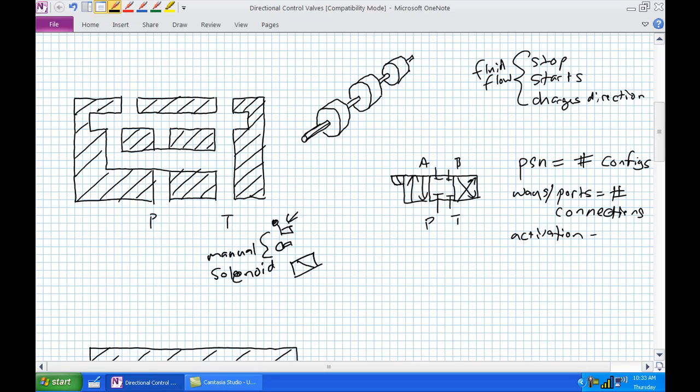Basically, it is an electrical means of activating a valve. So like I just said about the spool here, that end of the spool, basically, if you've got this little electromagnet here, which is the solenoid, and you've got the spool in its de-energized state, nothing's going on, all of a sudden you turn a switch, or a computer turns a switch somewhere.